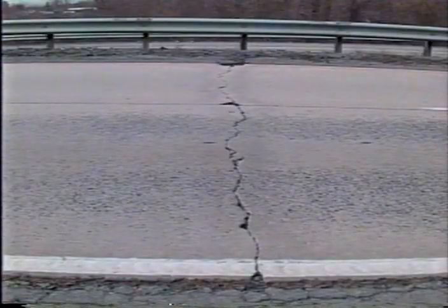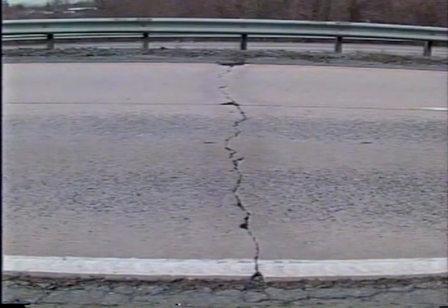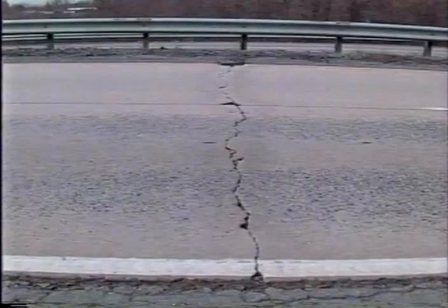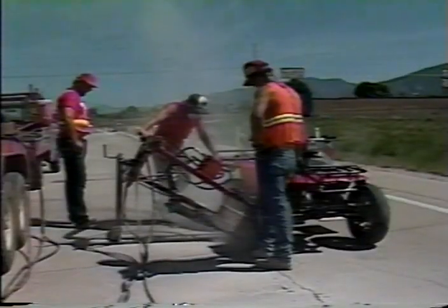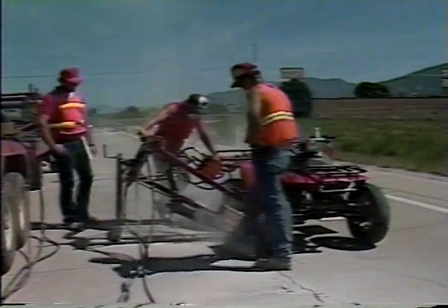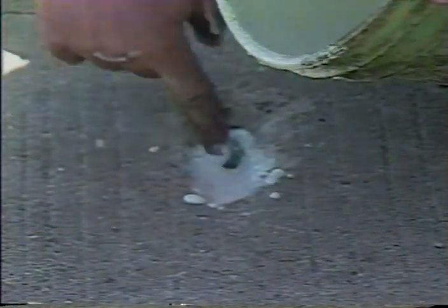Transverse cracks may be repaired by retrofitting dowel or tie bars across them. Then in the overlay, the retrofitted crack must be sawed and treated as a joint. Working longitudinal cracks can be cross-stitched. This involves drilling holes at an angle through the crack and grouting in deformed tie bars. Cross-stitching will hold the crack together, but it will not necessarily prevent the crack from reflecting through the overlay.